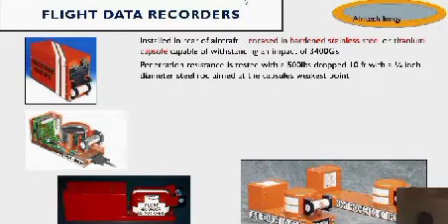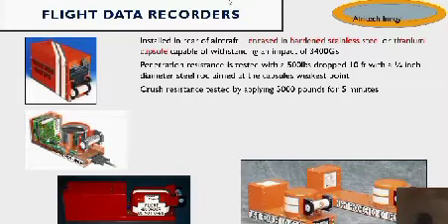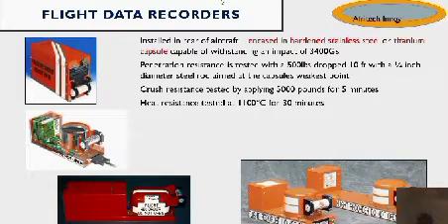Penetration resistance is tested with a 500 pounds weight dropped 10 feet with a 1/4 inch diameter steel rod aimed at the capsule's weakest point. Crash resistance is tested by applying 5,000 pounds for 5 minutes. Heat resistance is tested at 1100 degrees Celsius for 13 minutes.